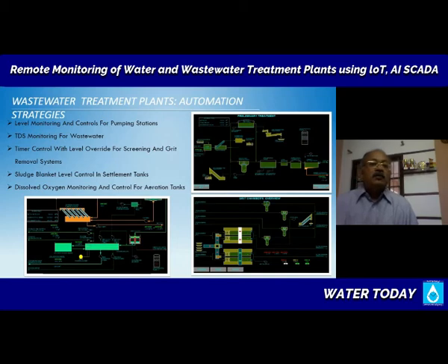Now, TDS monitoring. TDS monitoring for wastewater, in many countries, is widely used where the groundwater is saline. Now, a lot of my work was done in the Middle East, where they do have groundwater, but it is very, very saline groundwater. So, if there is groundwater ingress into your wastewater system through damaged sewers, etc., then TDS gives you the story.